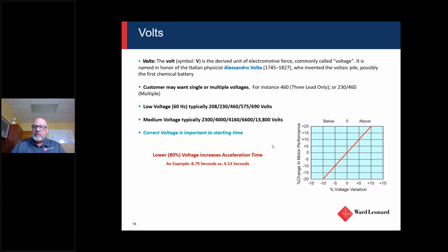There's higher voltages above that, but when we talk about 7,200 volts to 13.8, for me, it's because that's the break in the insulation. When we repair things and work on things, the medium voltage resins and materials are usually rated at 6,600 volts and below. If we go above that, we have to change a lot of things: resins, materials, lead wire. There's just a whole other level to deal with past 6,600 volts. So I apologize, that actually should be down here.